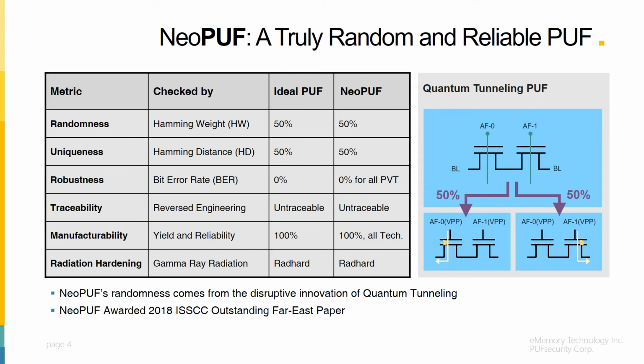Through statistical analysis of min-entropy using NIST SP 800-90B and NIST SP 800-22, Neopath can be defined as a perfect steady entropy with ideal randomness, uniqueness, and stability. Neopath is a real hardware PUF, needs no helper, is immediately ready in microseconds, and can achieve 0-bit error rate in all process, voltage, and temperature corners.